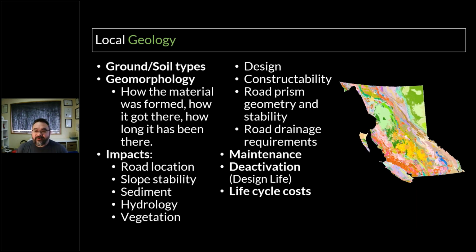You end up having as much impact from getting the investigation done as you will from your development. So that estimation of the subsurface conditions, and broadly how the slope is likely to behave, is critical not only to the details of how you'll build the road meter by meter, but to how it's going to interact with or influence the overall slope.